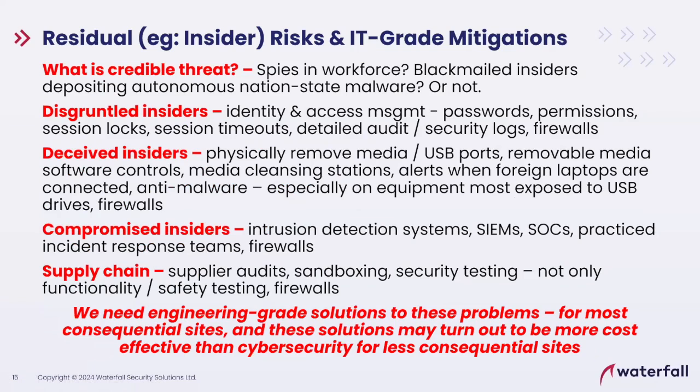What's left? Well, think about it. We have put SL4 and better. We put engineering grade protection at the criticality boundary, at the IT/OT network. The zone on the OT side that's connected to the gateway, that's connected to the network engineering device out to the IT network, that zone has really strong protection on the IT side. Does it need SL4 for the conduits to the other zones? Maybe not. It depends on what's left risk-wise.